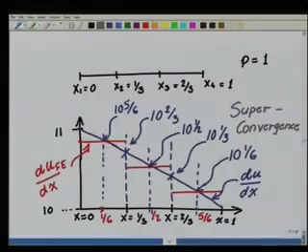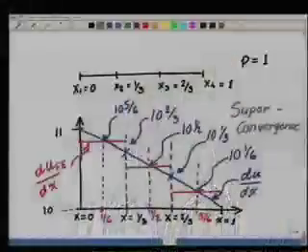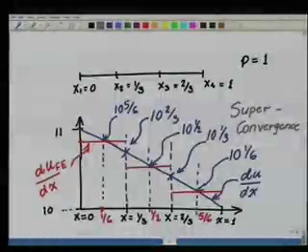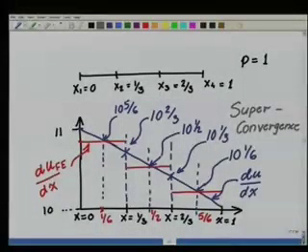Even though we have shown it with a very specific example, for linear approximations what we can show is that when we have any other loading, in all those cases, the midpoint turns out to be a point of very good derivative information. That is, the derivative of the finite element solution at the midpoint of the element is very close to the exact solution, in fact closer to the exact solution than the derivative evaluated at any other point in the element. That is why it is called a point of superconvergence.